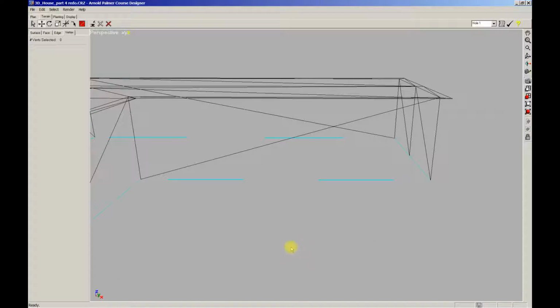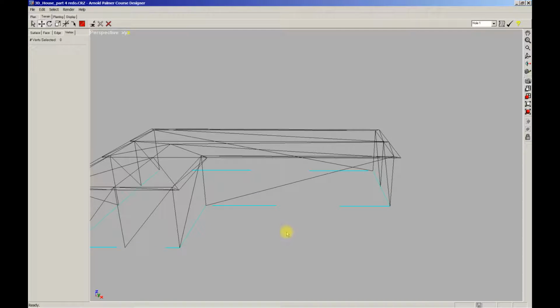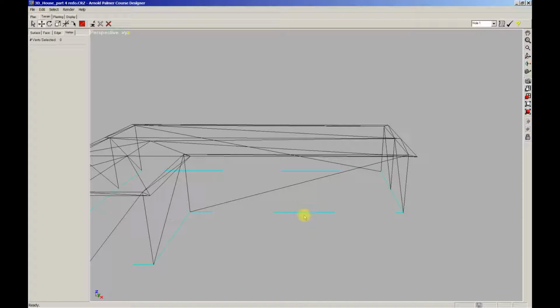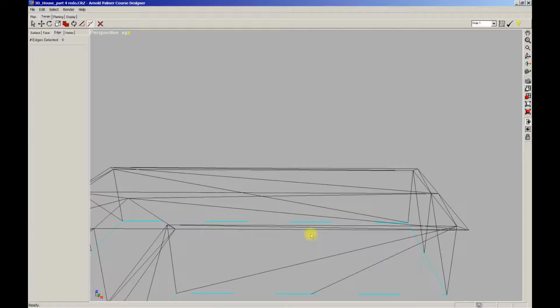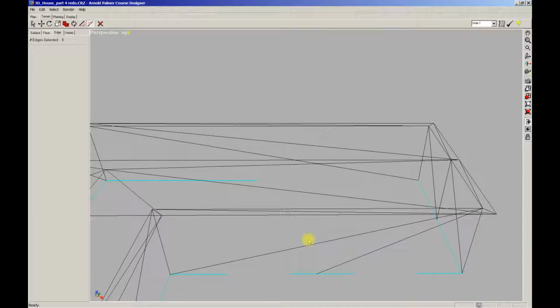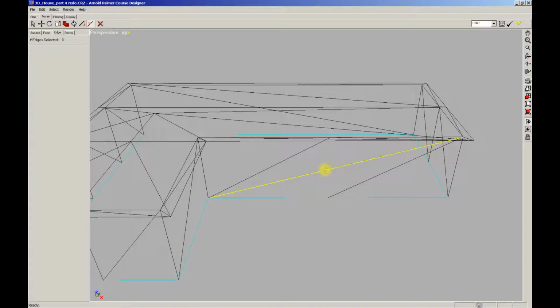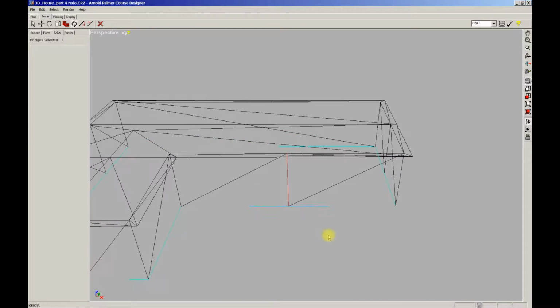I'm going to go ahead and open it up into the full view, and the overhead door goes here, so I'm going to split this down the middle. I'll use edge and split. I'll split that there, and then I'll go up to the top and split it here, and then I'll rotate this. Now I've got 2 boxes here. I'll put the overhead door in this box. I'm going to put a bay window on this side.